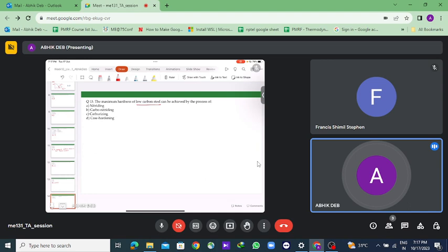So the steel here is heated to the ferritic stage of 500 to 550 degrees to facilitate the conversion of ammonia to nitrogen and hydrogen, and the diffusion of nitrogen to the surface. So remember this, that for nitriding the heating is done till the ferritic stage.